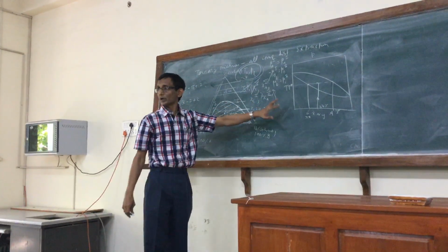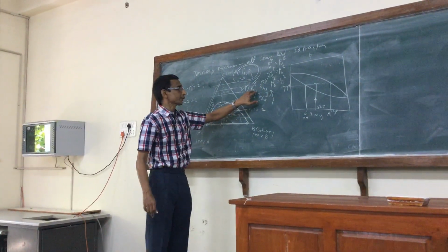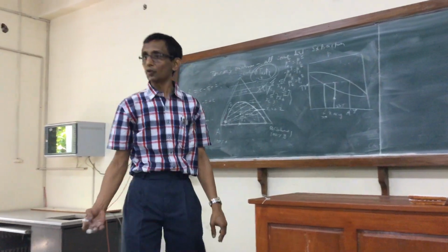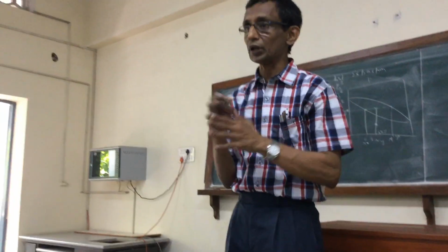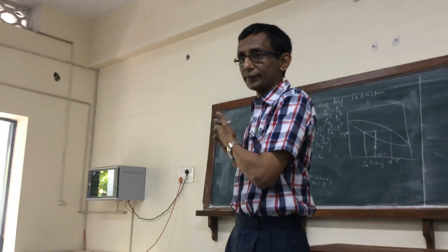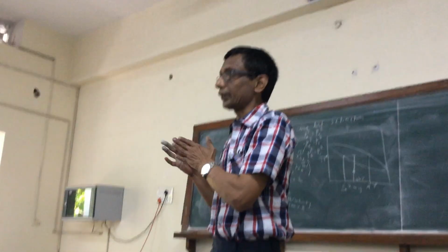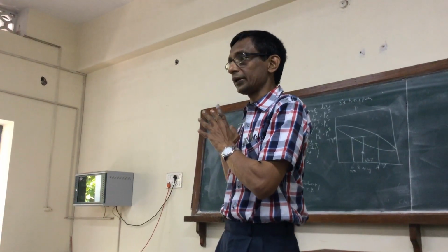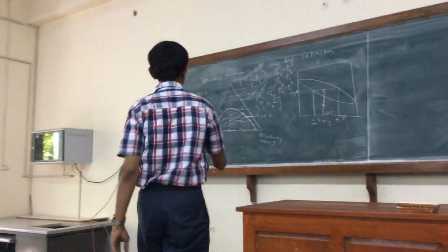What about the other mole fractions? Clearly, once I know XC1 and XA1, the other, XB1, is determined by the mole fraction constraint, which I don't include as a set of equations because I've already taken that into account. When I list the variables, I list only the independent mole fractions. So the other variables are automatically determined. That's very important to keep in mind.